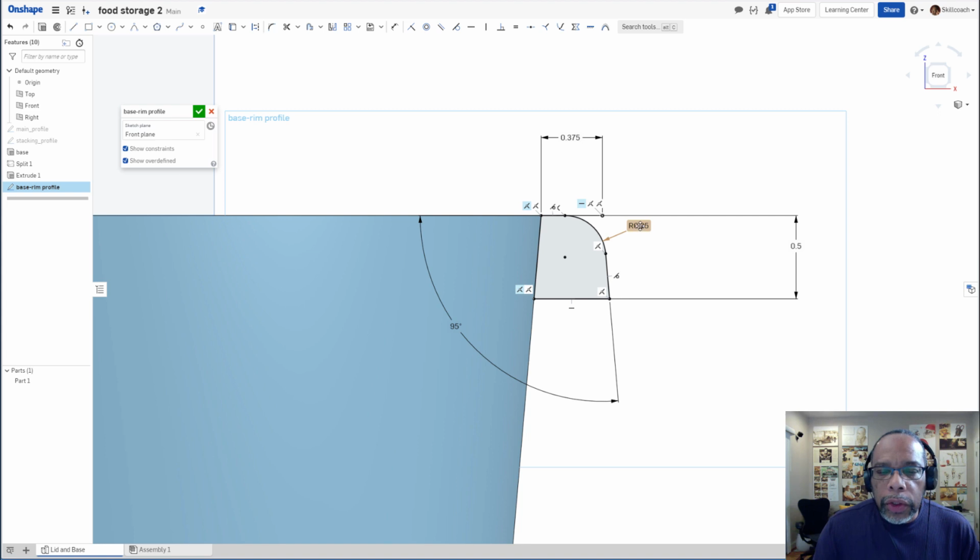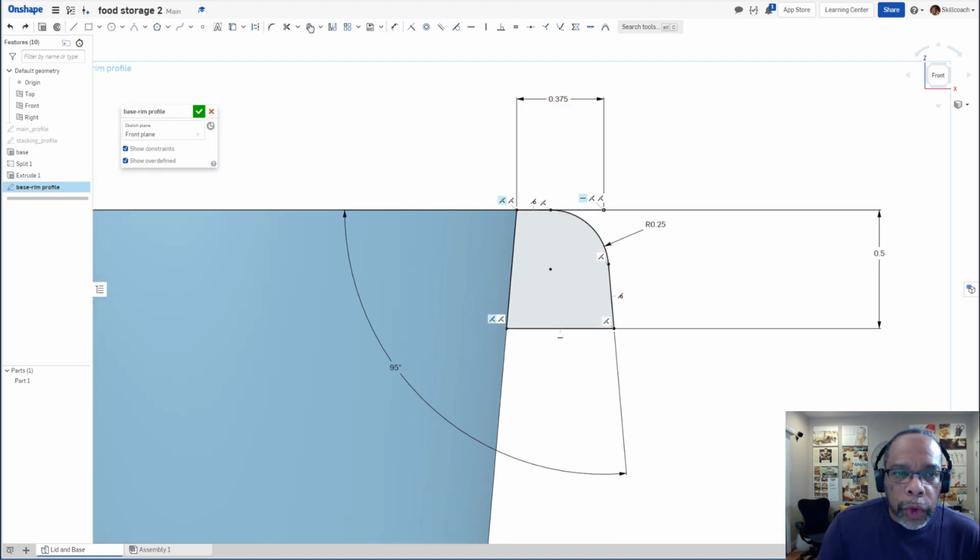I'm going to leave it roughed in for just a moment, because the next step in laying this out, I'm going to offset to get the rim thickness. Right now this is a solid section, but we really want a thin protrusion to sweep around. So if we go offset and we pick here, here, and here, flip the direction and make it 0.09, which is the wall thickness we're going to use, 0.09. Let's try that again. Let's go undo, undo, and re-invoke the tool and pick here, here, here. Let's drag this time so that it doesn't, now we'll make that at point.